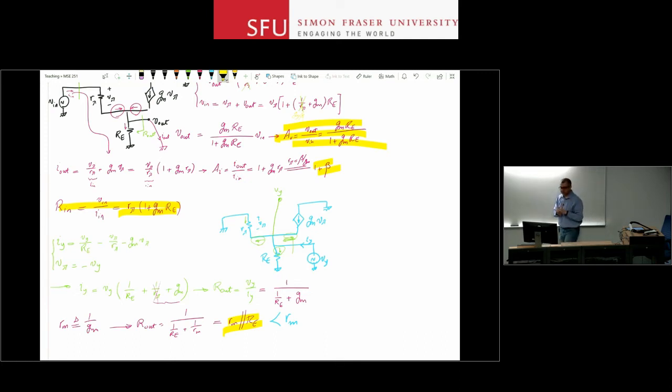It doesn't have that much of a gain. Like common emitter, it ticked 2 of the 3 boxes as well. It had a large voltage gain, a large input resistance, but unfortunately the output resistance was large. So you, again, give and take. So again, we have to give up on the value of voltage gain, but we get a very small output resistance. Where do I use a common collector stage?